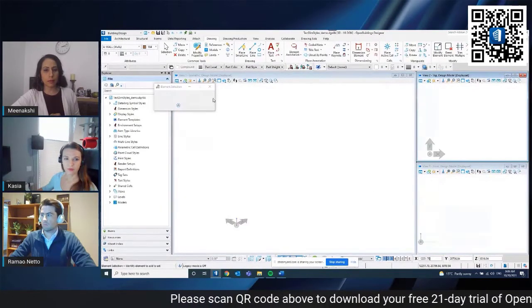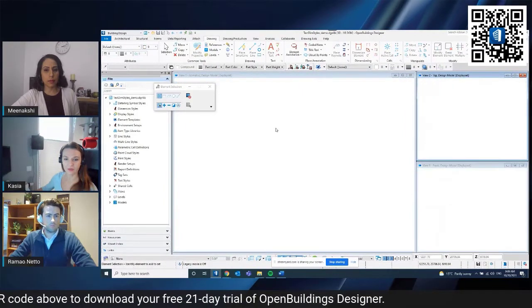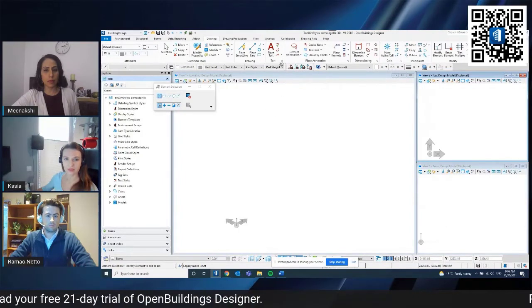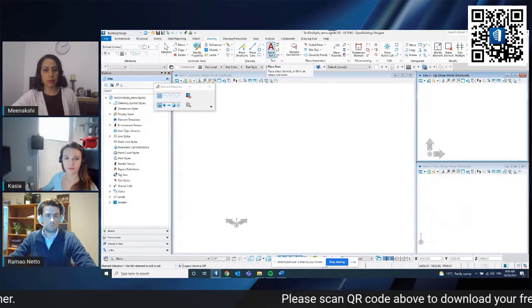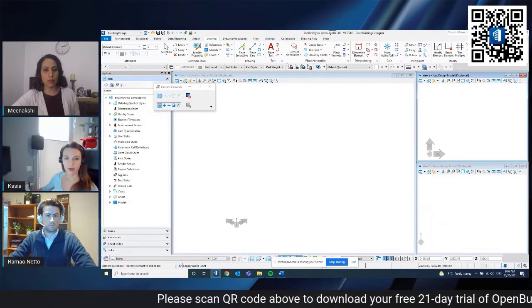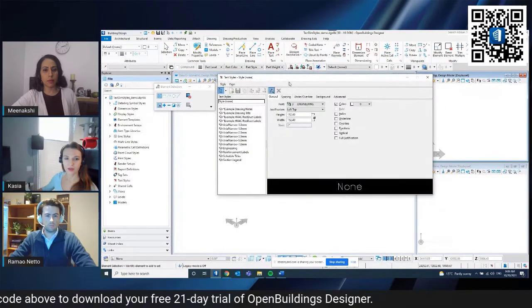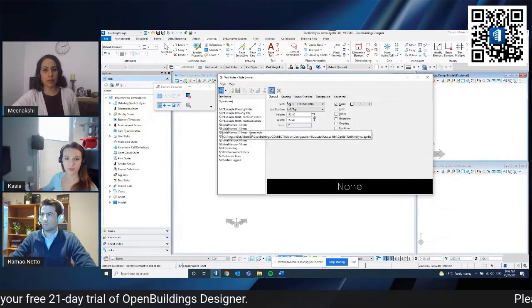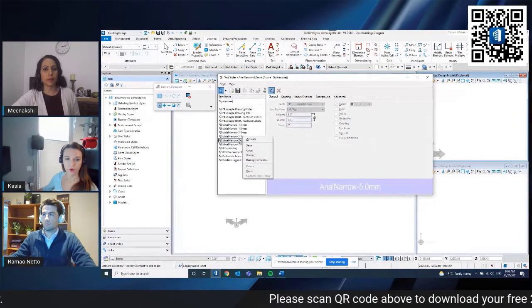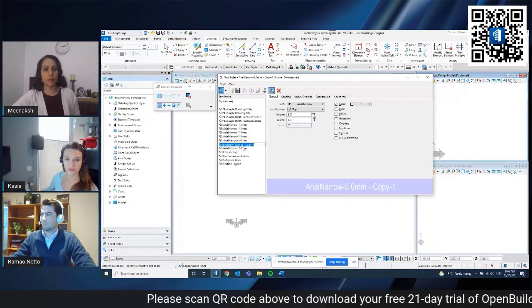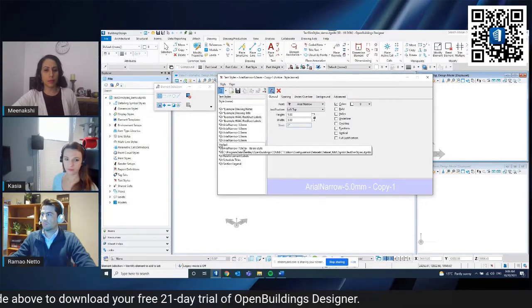it opens this new file for me, and here's where I can start the customization of my data, of my standards. I can prepare my own style for the text. So here in the drawing section, we have the text section on the ribbon bar. And when I hit this small button for the management of text styles, I get this dialog box. And here is where I can create my own style. So I will do it through copying an existing text style, and I can call it new text style